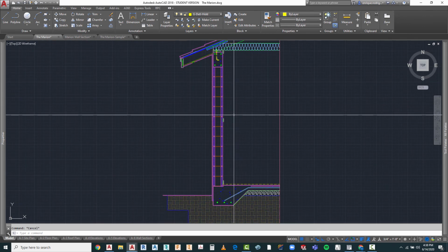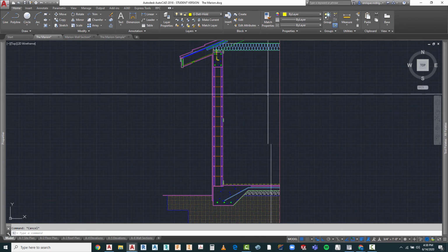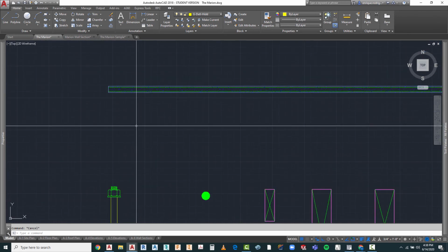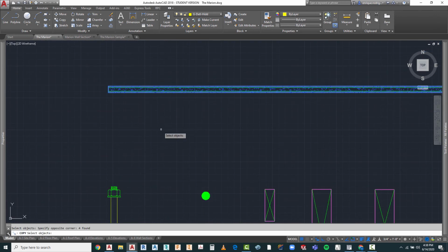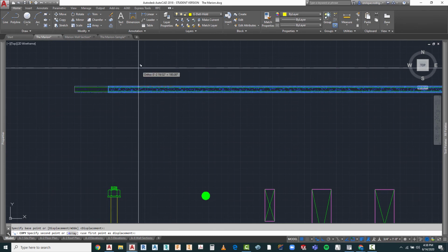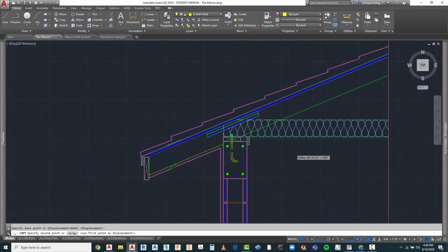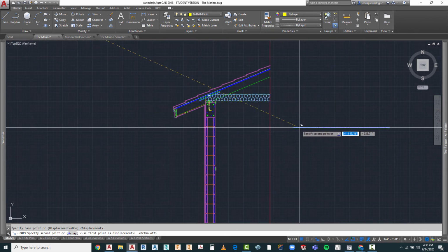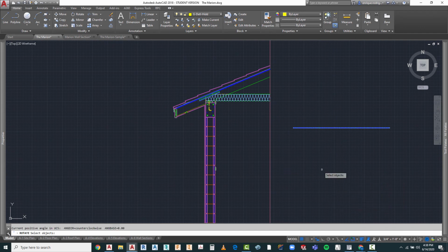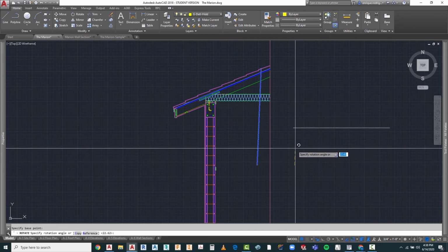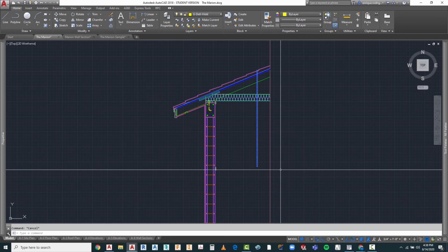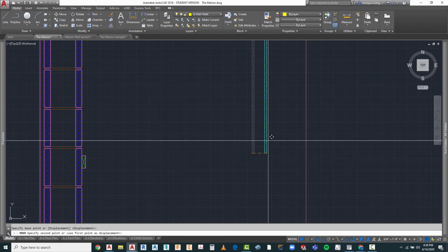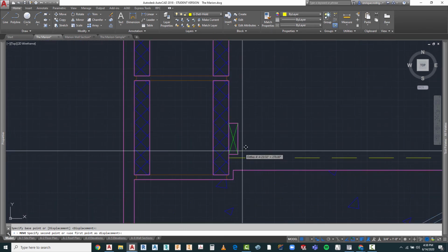Okay, so let's go ahead and put our drywall, our vertical drywall here. If you take a look at this material, I'm going to copy it. We're also going to be using it in the ceiling, so rather than having to copy that one twice, I'm going to bring one over to here. I'm going to do that one, and rotate it, make it vertical on our F8. I'm going to move P for previous, and bring that guy down and place it somewhere down in here.